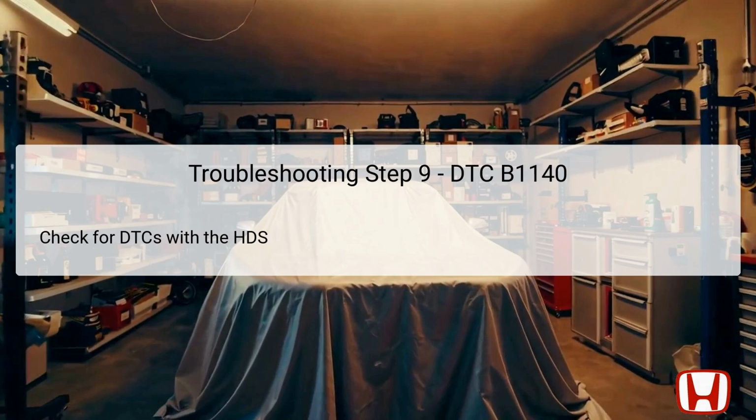Alternatively, if DTC B1140 does not return, it indicates that the door multiplex control unit is the issue, necessitating a replacement of the power window master switch or further investigation of the 4-door, 2-door variants based on your vehicle model. Each step in this final analysis is integral to ending up with a successful repair.